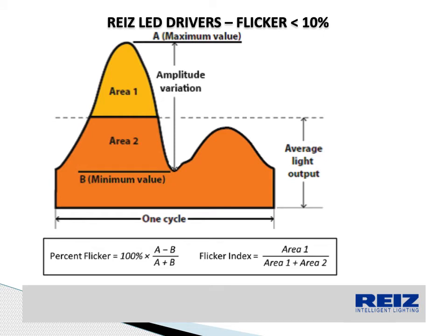International standards limit the level of flicker to less than 10%, but unfortunately, in India there is no standard for flicker, and this important aspect affects factories even more because they have moving machinery, moving parts, and flicker forms a stroboscopic effect on any moving part, which can cause further dizziness, headaches, and eye strain.